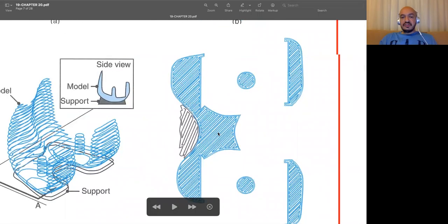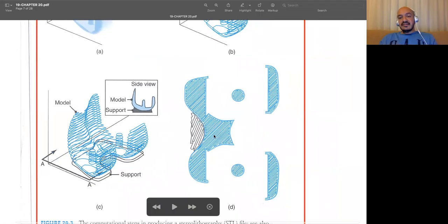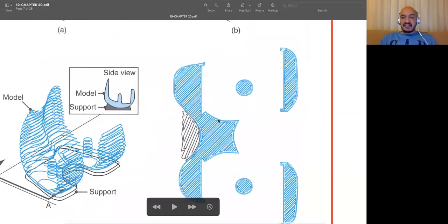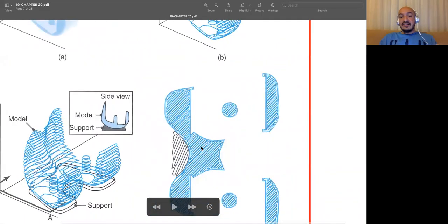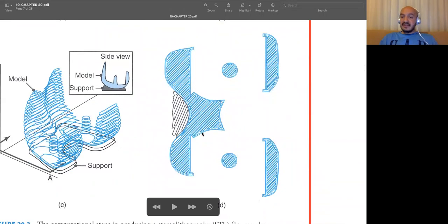And that's an important issue. Depending on your settings, you may fill it completely, you may have 100% infill, or you may have 20%, or just keep the interior empty. It's up to you. You may just have the shells. So this outer contour is called shells. And if you look at it carefully, we have two shells, and in the interior part of this slice we have a kind of zigzag pattern. It doesn't have to be zigzag, but there are different ways to fill the interior.